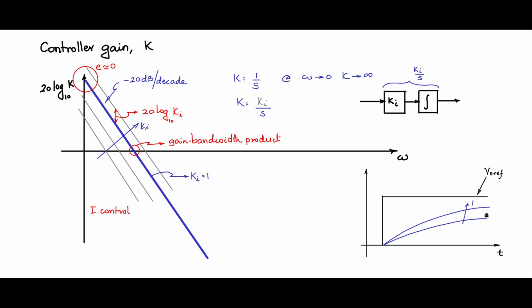So here also Ki increases in this fashion. The one that we have chosen could probably have a response coming like this, and you could see it reaching steady state quicker. If you choose a higher one, it would probably go much quicker, and then you choose one that satisfies you on the oscilloscope.